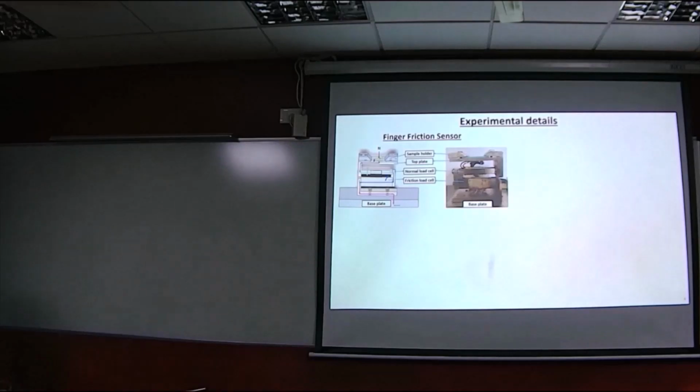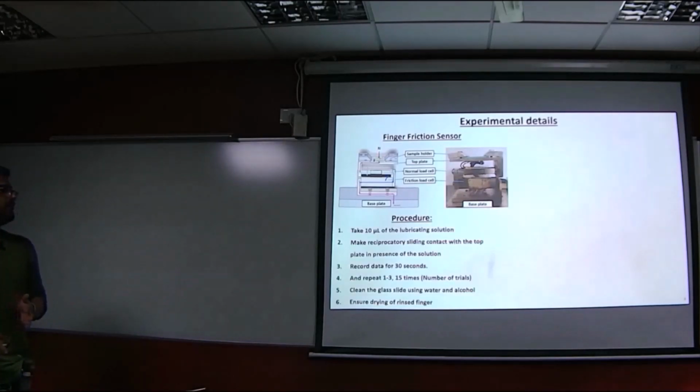To measure friction, we have designed an in-house sensor which works on the principle of strain gauges. It is capable of measuring both the normal force as well as the tangential or frictional force simultaneously and independently. To perform the experiment, we take about 10 microliters of the respective lubricating solution and pour it on the top plate.